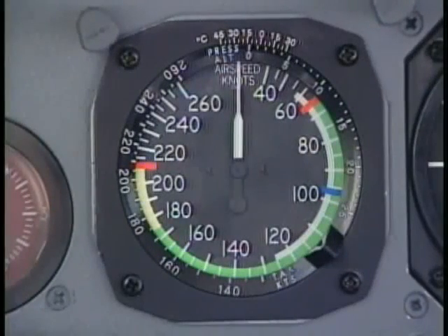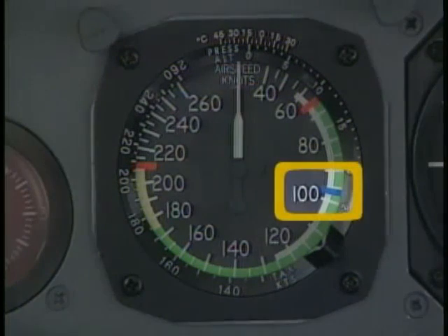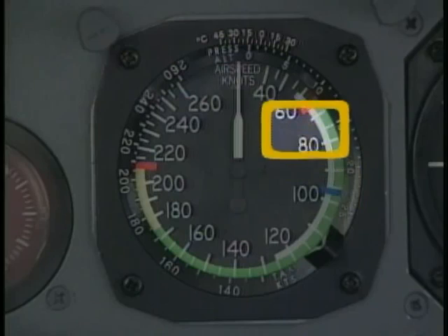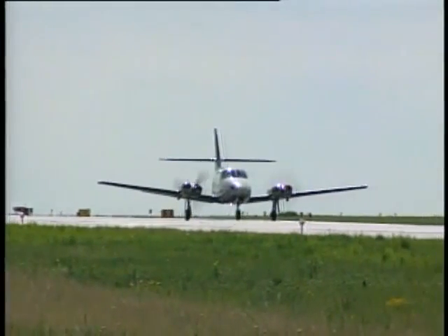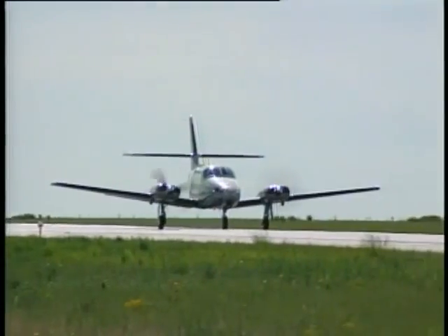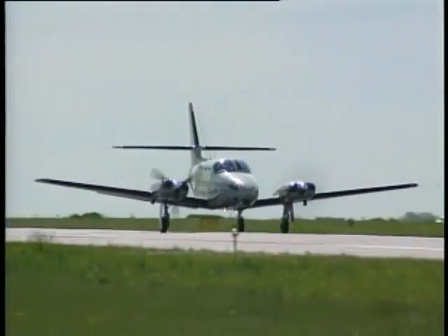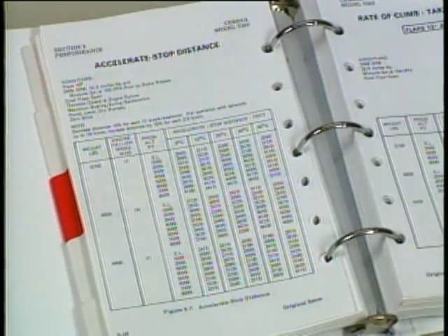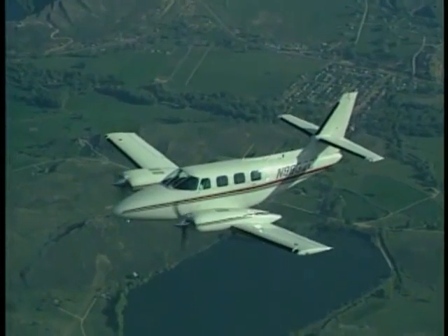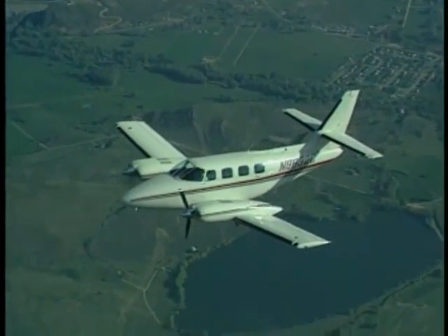For example, the pilot will need to understand the meaning of several V speeds, such as VYSE and VMC. Performance data, including accelerate-stop and accelerate-go distances, and systems unique to the airplane can be discussed using the pilot's operating handbook as a guide. And of course, engine out characteristics and procedures will need to be covered extensively.